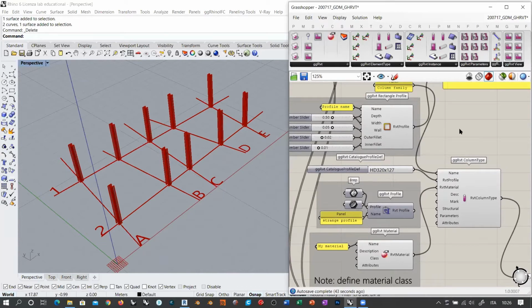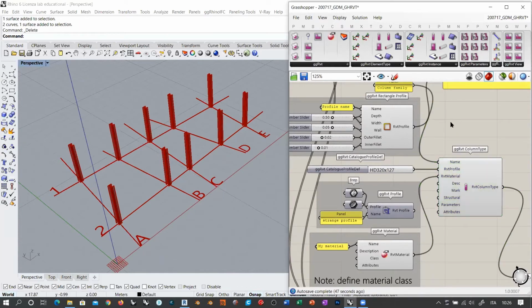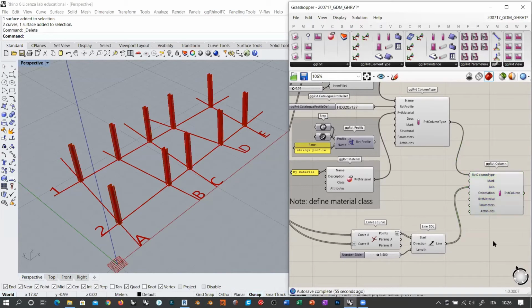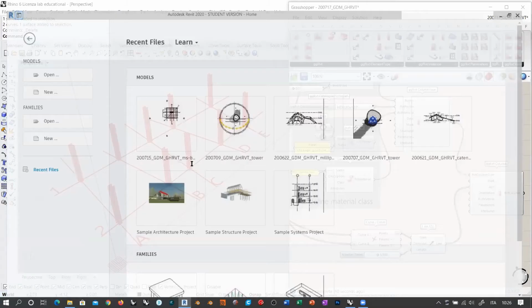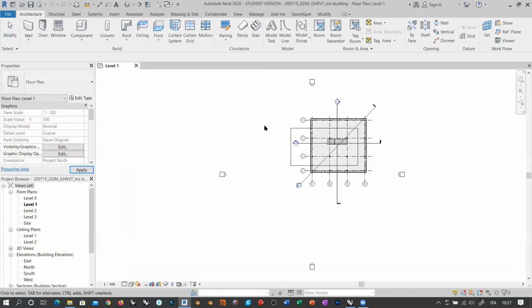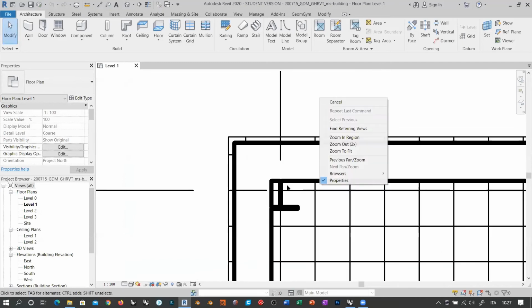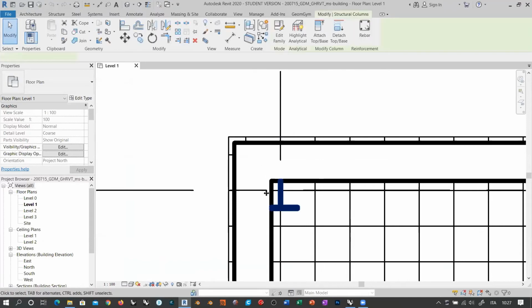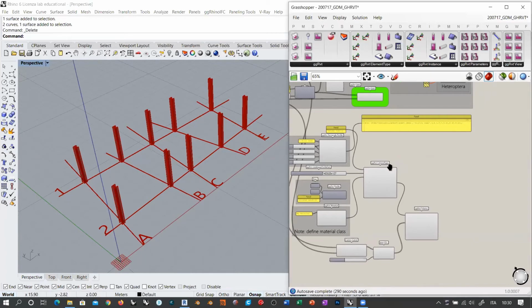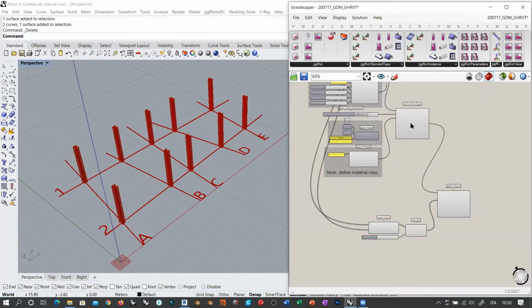One consideration, remember, and this is not for Grasshopper use, this is for Revit. When you define a structural column, remember that in Revit, structural columns don't blend with, for example, architectural elements. So once you have, well, let me show you the file that I already prepared. This is a glimpse to what we are going to find later on. You see that we have a structural column here, and this is not blending with the wall, of course, because they have different functions.